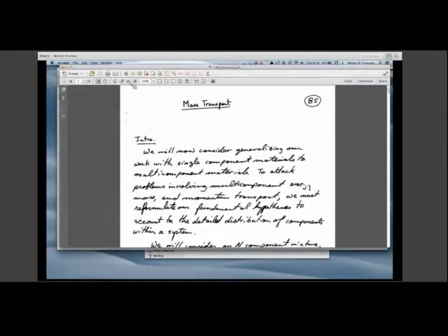The effectiveness goes down because you can't get into the internal area of that particle fast enough to react and form B and get the B out. So lower values of effectiveness factor mean that the catalyst particle is suffocating in a sense, or starving to get reactant in and product out. So are there any questions about this before we move on?